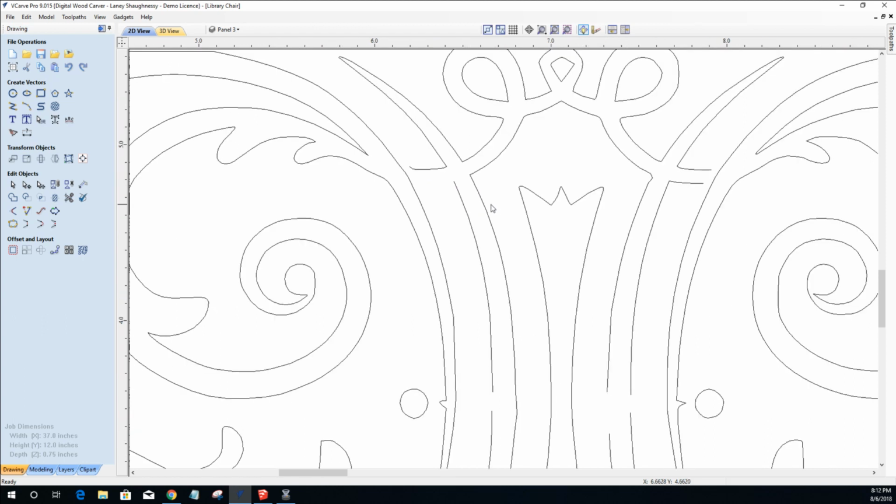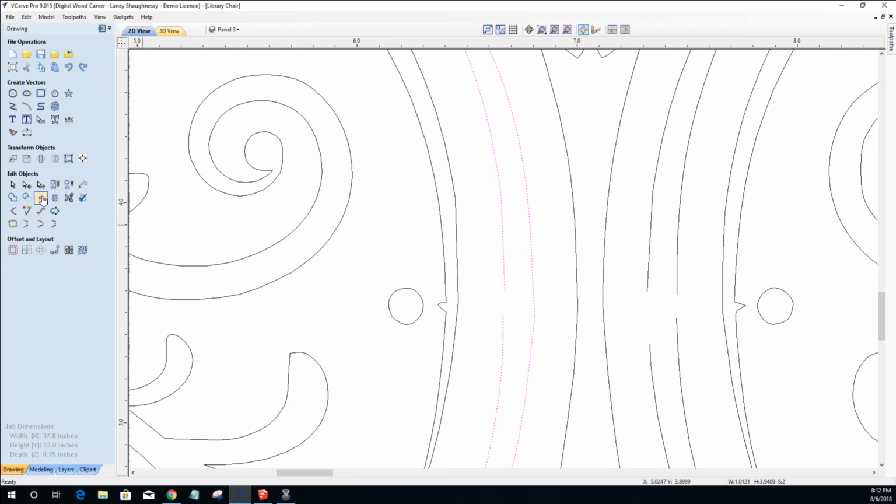Let's do this in a little bit of an order. Let's take and grab this one up here with that lower one and join with a smooth curve, because it's wanting to pull that line. It's wanting to come around in this order. Now I can add this line into the mix and join with a smooth curve once, and then again twice at the bottom.